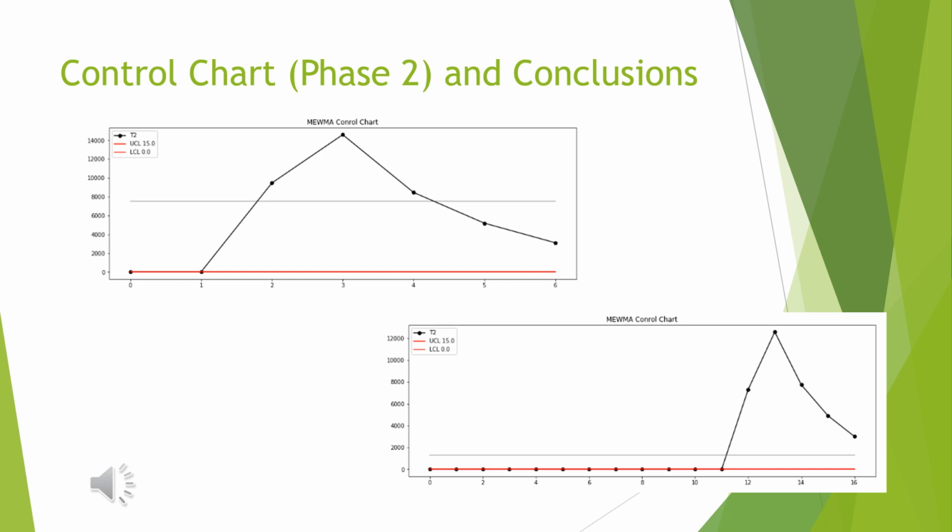What can be seen is that at a point, all of the parts start to become out of control. And so what I would recommend as part of this process and evaluation is when stuff like this happens, to have some sort of a trigger point that causes the system to stop and to be reevaluated, because more than likely it's a calibration issue or something got off in printing and it's causing all of the data to be completely skewed one way or another. And if reset, it could possibly get things back on track and under control.